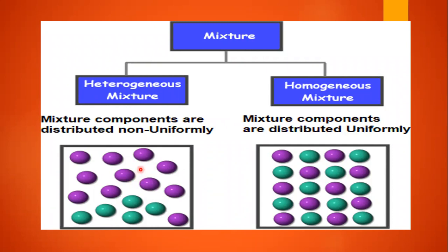So if we maintain some rich mixtures, that means a rich amount of fuel is there, and we are going to reduce the air quantity and increase the fuel quantity. Then the equivalence ratio will be 1 to 1.2 in case of a heterogeneous mixture, which we need to maintain to have complete combustion. Here 1.1 to 1.2, and here 1 to 1.2. Those are the somewhat rich mixtures. Here even stoichiometric will do complete combustion.